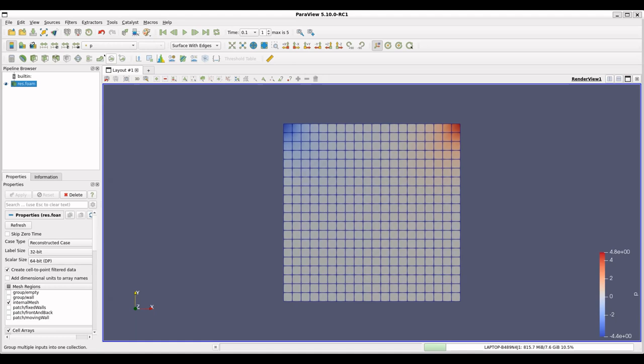There is a command called foamToVTK. If you do that, it will convert all your OpenFOAM time folders, the results, into a VTK folder, and then you open your Tecplot and load the VTK. From Windows it can be done. It doesn't depend on the operating system. If you can open your Tecplot in any operating system, you can just do it.